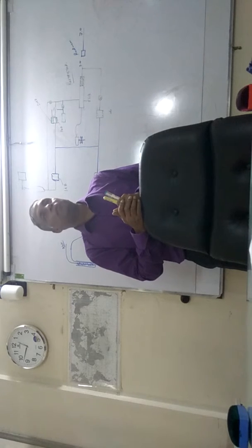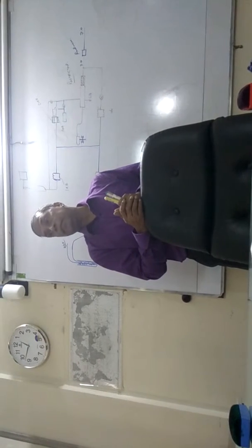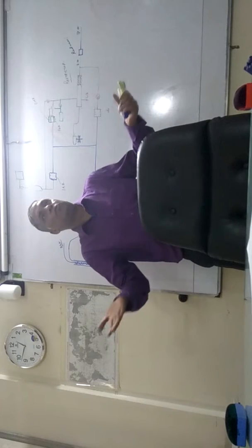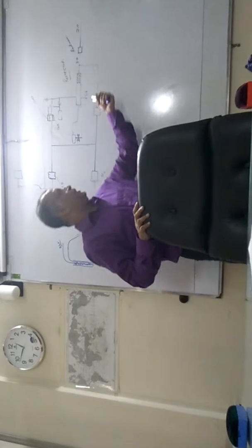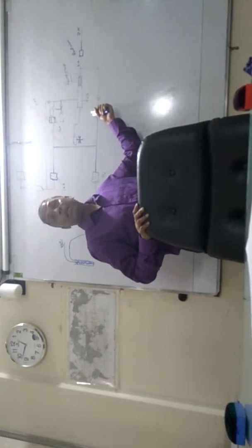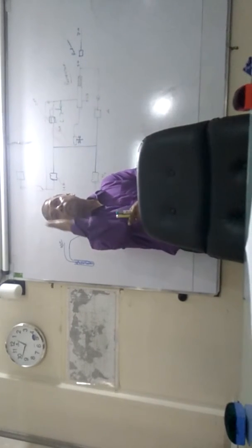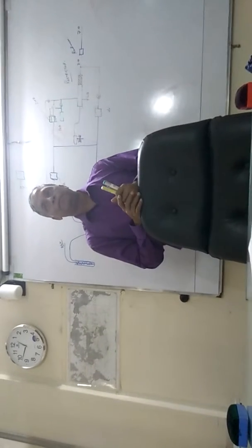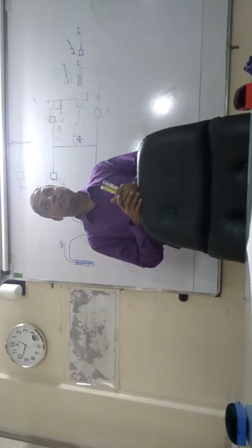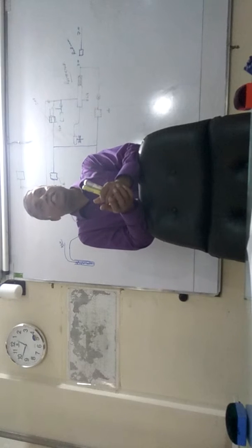Okay? So supposing we want the jacket cooling water temperature to be maintained at 80 degrees C, which is quite normal for our plants. Accordingly, we will supply some air in this bellow so that the red dial will be positioned at 80 degrees C. This is our desired value. Understand? So what is the desired value, definition wise?